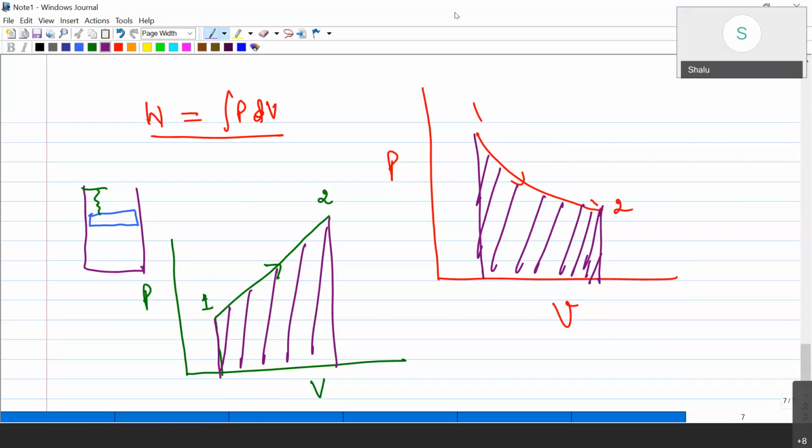In a transient process, when we consider the energy of the system, we take only internal energy, assuming kinetic and potential energy are zero. For a closed system, we have some tank-like arrangement that is stationary, so we do not have any bulk motion of the medium. So if nothing is mentioned in the question, we can take the internal energy of the system as its total energy. Yes.